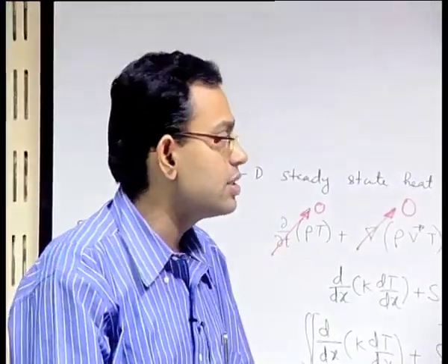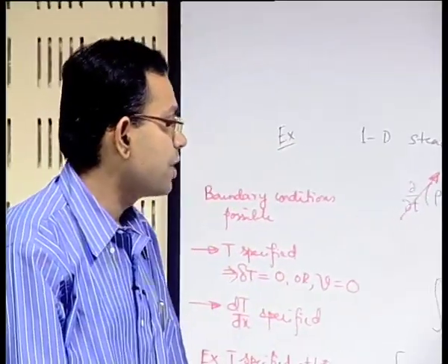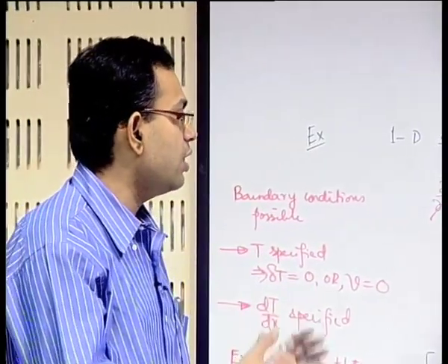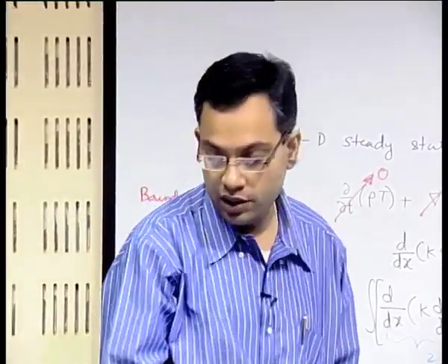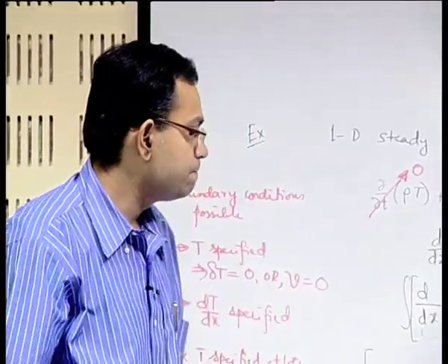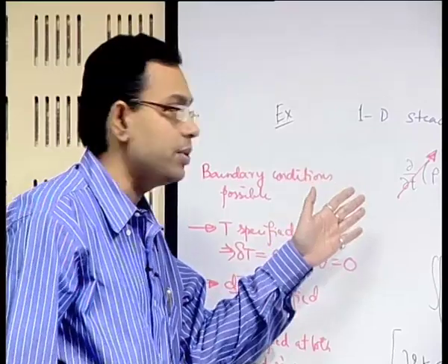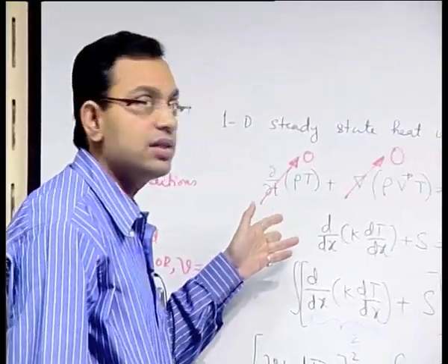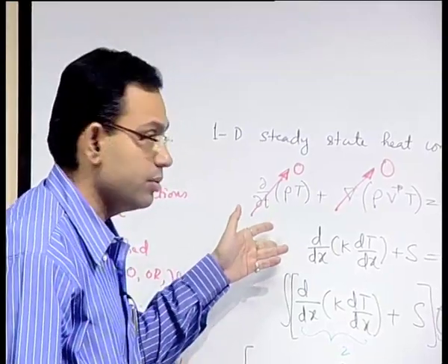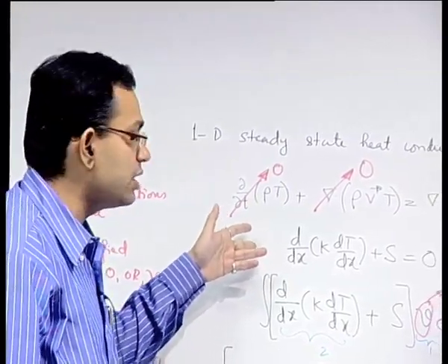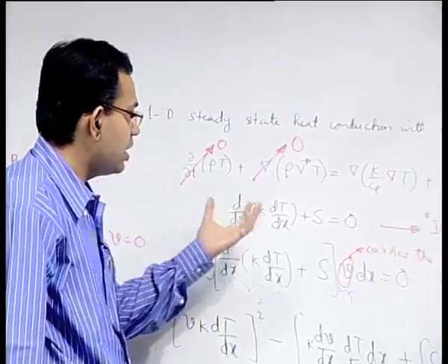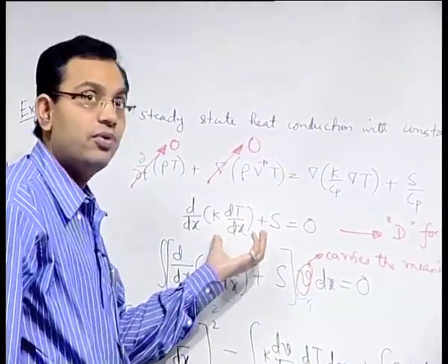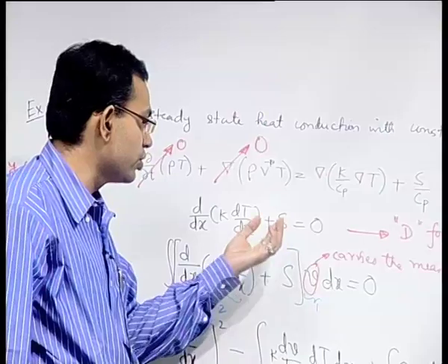We continue with our discussions that we started in our previous lecture, that we are now going for a variational formulation for solution of the differential equations. To do that, we have taken up a prototype example, a one dimensional steady state heat conduction problem. In it, we have come up with this particular simplified form with the constant source term.